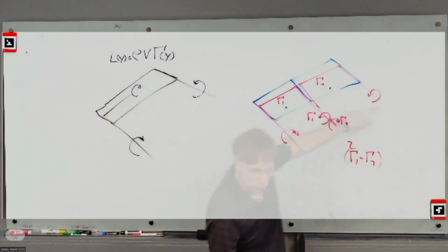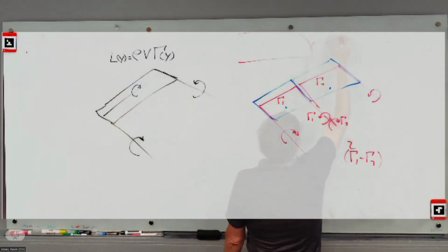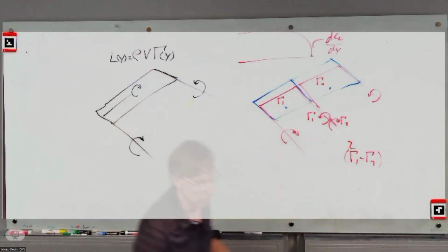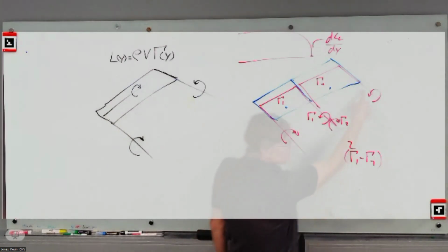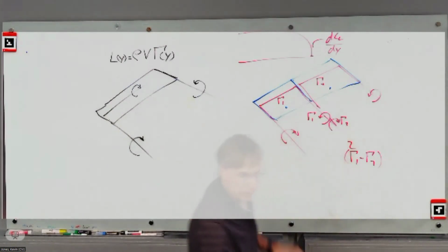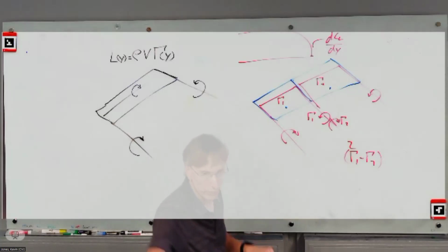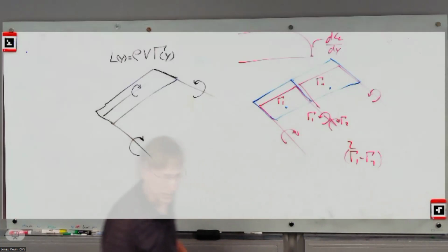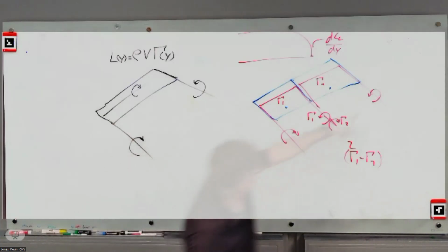The tip gets the strongest one because if you look at the lift distribution along the span, the CL of Y, it gets quite steep up there. When that gets steep, the local gamma of Y gets strong. So by far the strongest is usually at the tip, unless they have some weird tip work, like a washout wingtip, huge taper or something like that. Usually it's maximum out there.